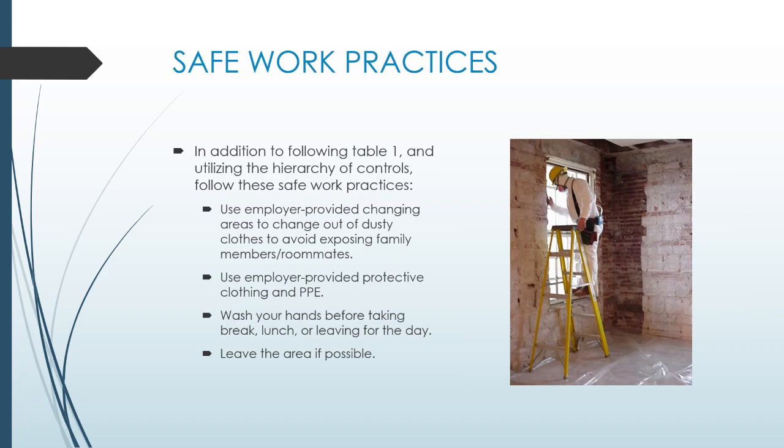So, some safe work practices. In addition to following Table 1, we saw Table 1 was the tools and the PPE. There are some other things we can do when working with crystalline silica. When working in those dusty environments, there are going to be changing areas where you can roll down coveralls and avoid exposing other people. Going home and throwing those dirty clothes in the laundry, now there's dust in your living room or your bedroom.